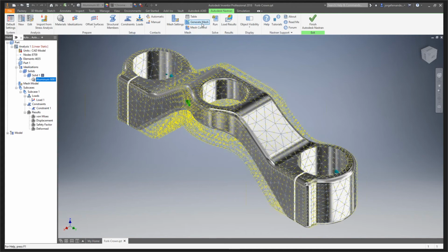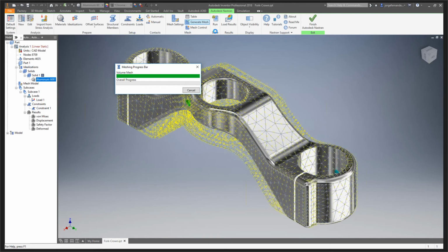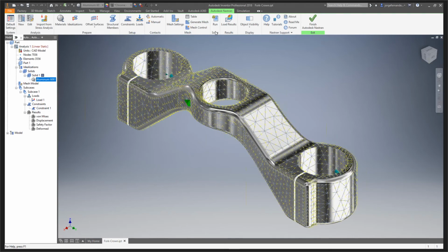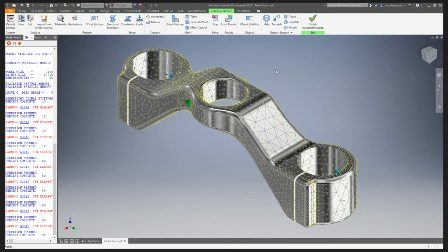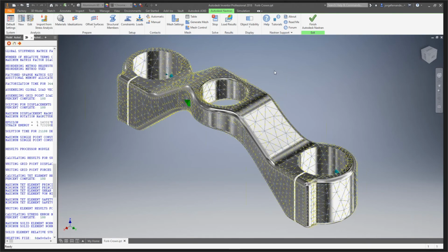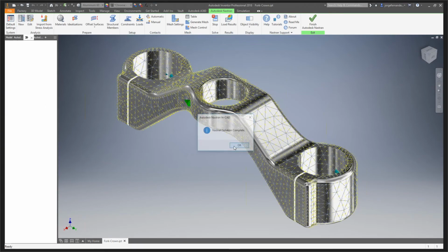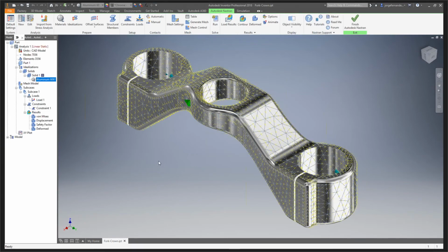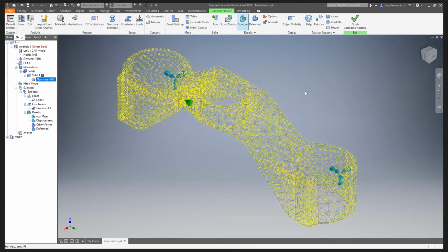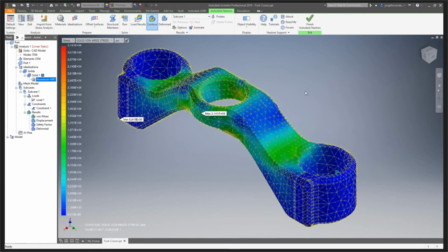All I have to do now is generate the mesh again, assuming, of course, those surfaces are still there, right? Right. Obviously, if you got rid of those holes and your constraints were to those holes, you might have to do a couple of things. But if it's small geometry changes, it should port straight over. Absolutely. In a few seconds here, I was able to rerun this again and see what the results will be. And hey, is it still within the limits that I'm looking for? It's getting a little closer now.